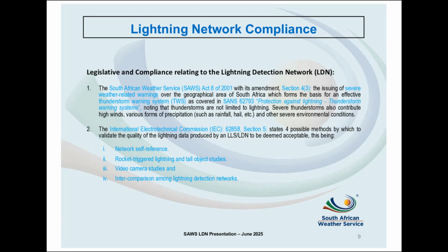Then, of course, with IEC 62858, Section 5, there is validation of our network that we needed to comply with, and these consist of the network self-referencing, the rocket-triggered lightning and tall object studies, as well as the video camera studies and the intercomparison amongst lightning detection networks or lightning location systems.